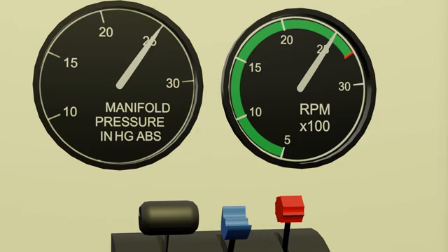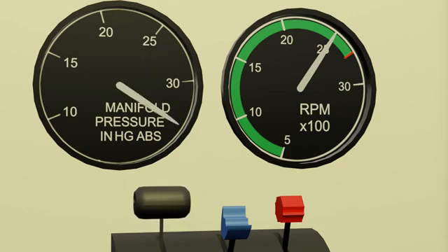As the climb continues to higher altitude, the manifold pressure will continue dropping. Is our engine losing power? Yes, indeed. The ambient pressure drops the higher we climb, and this limits the amount of air and fuel the engine is able to draw. This is why superchargers and turbochargers exist. They can sometimes boost manifold pressure above 29.92 inches for extra power.